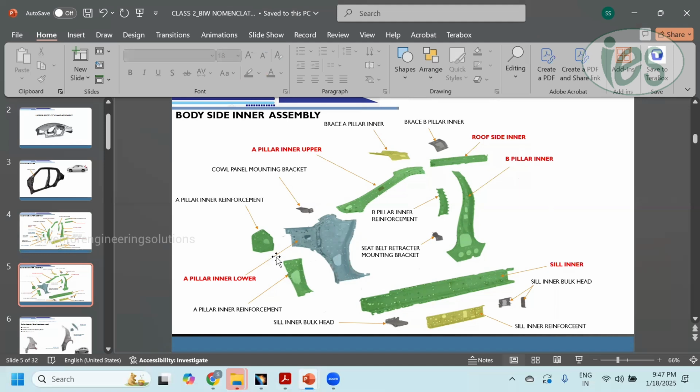Okay. So due to the front wheel which will come here, we can't move this wheel arch outside. The same way, this area is the lower knee entry and exit point. This is the door. That means when you are entering and exiting, this is the area your head and leg will get impact. So that is the reason they have cut out this one.